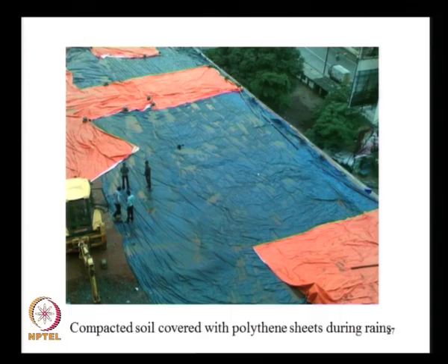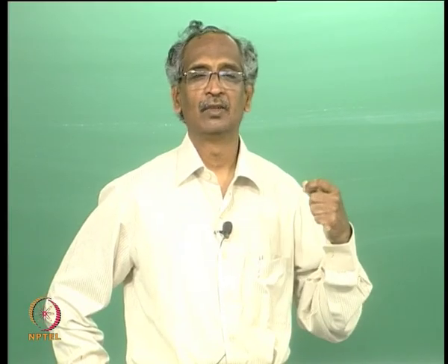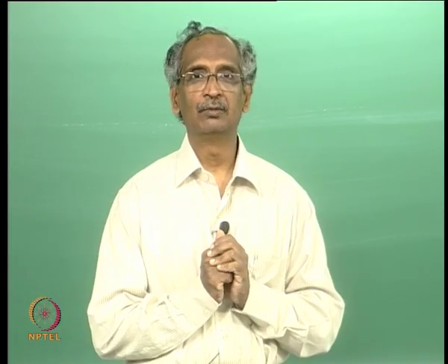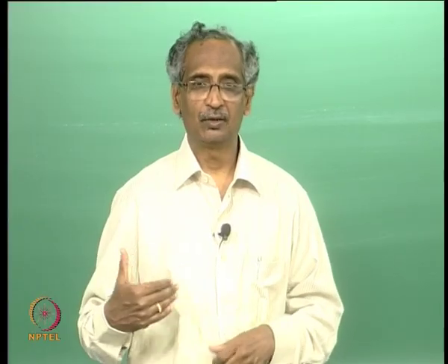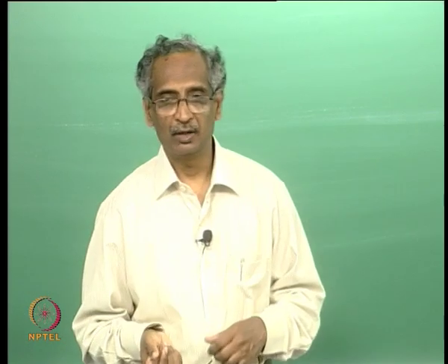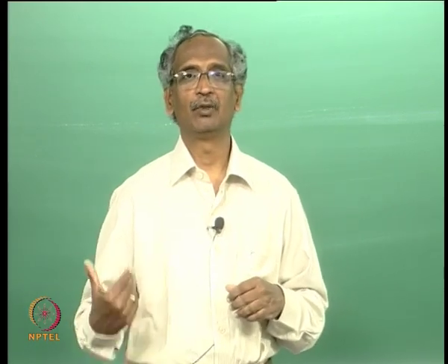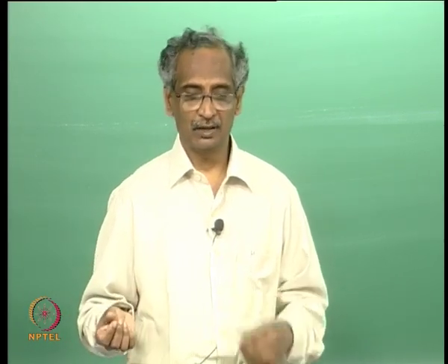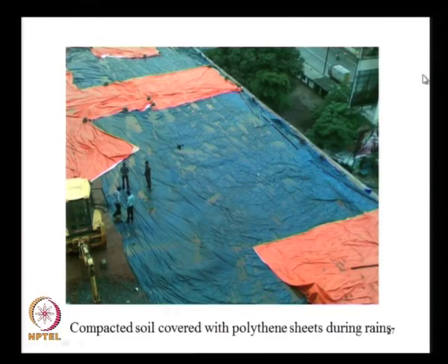If you allow the rainwater to go in, it is very difficult to get adequate compaction quality, because, as you know, wet soil is very soggy and you cannot really compact it. So at this particular place, even during a small drizzle, the entire soil area was covered with polythene sheets, so that the rainwater does not penetrate into the soil.